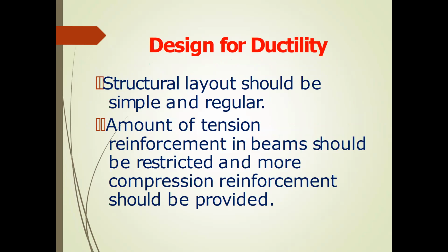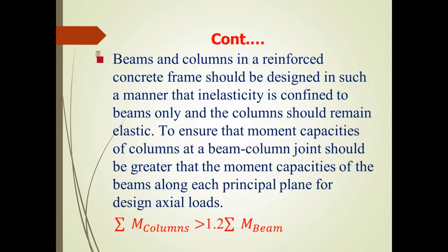Structural layout should be simple and regular. The amount of tension reinforcement in a beam should be restricted and more compression reinforcement should be provided. Beams and columns in a reinforced concrete frame should be designed in such a manner that inelasticity is confined to the beams only and the columns should remain elastic.